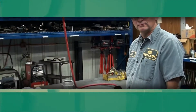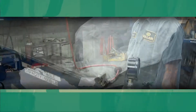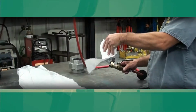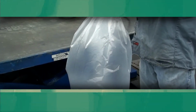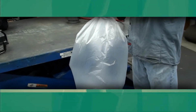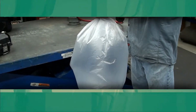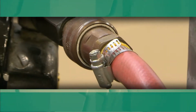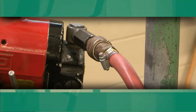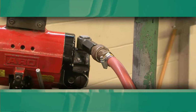To illustrate this, let's take a look at a simple experiment. This bag has close to a 5 cubic foot capacity. Just a small leak can fill the bag within 30 seconds. That's a 10 cubic foot per minute loss of air, which is an energy hit equal to about $100 a month. Identifying the sources of leaks and performing minor maintenance alone can potentially save your company thousands of dollars per year.